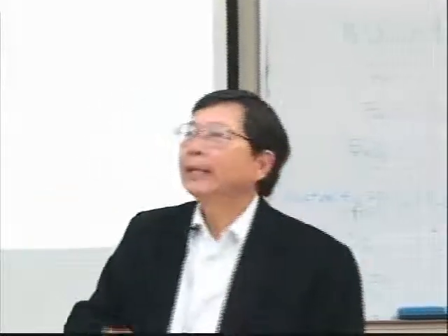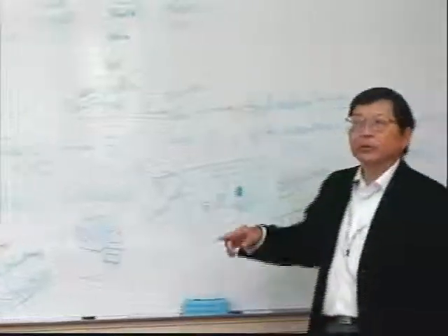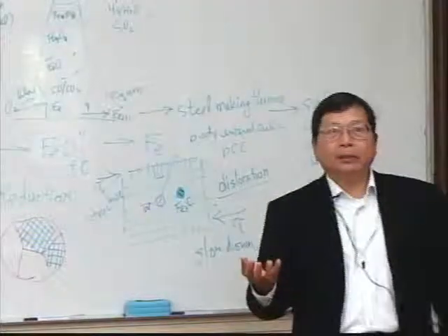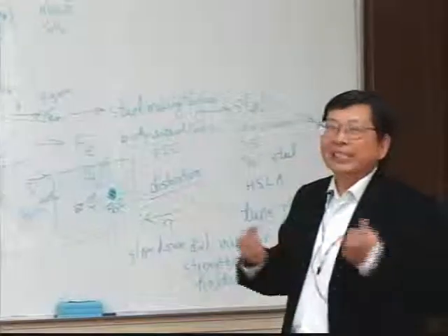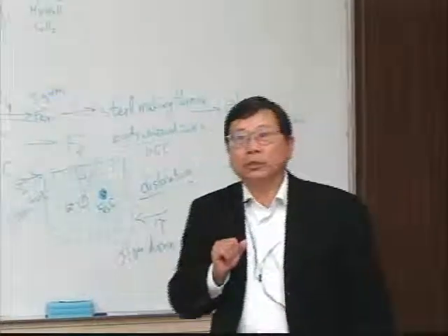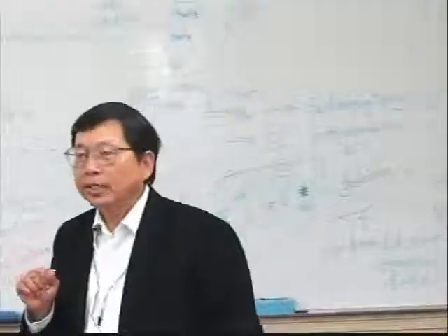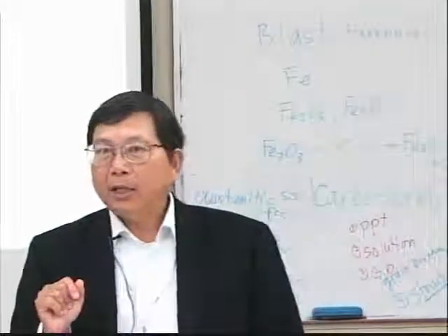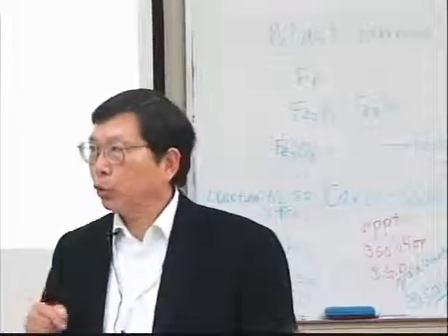So people try to make aluminum stronger and stronger, and that's why, if you look at aluminum, there are different grades. They add alloying elements to make it stronger, like copper, zinc, and silicon. That's just like this, so that the dislocation cannot move. And when you use aluminum, it also always has to be heat treated.